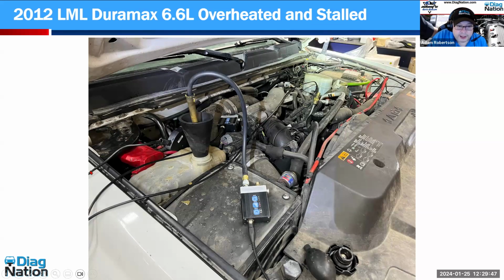Right here is my high amp current probe on my starter cable. Now I want you all to just stop and think. Adam, it looks like you're going to do a cranking relative compression test with the high amp probe. Yes. You're going to look at a sync of one of the injectors for counting purposes. Yes. You're going to look at the pressure, the point of this class, in the degas bottle to see what the cooling system does. Yes. And you're going to look at the pressure in the crankcase to see crankcase pressure. Yep. We're going to do all of that at once.